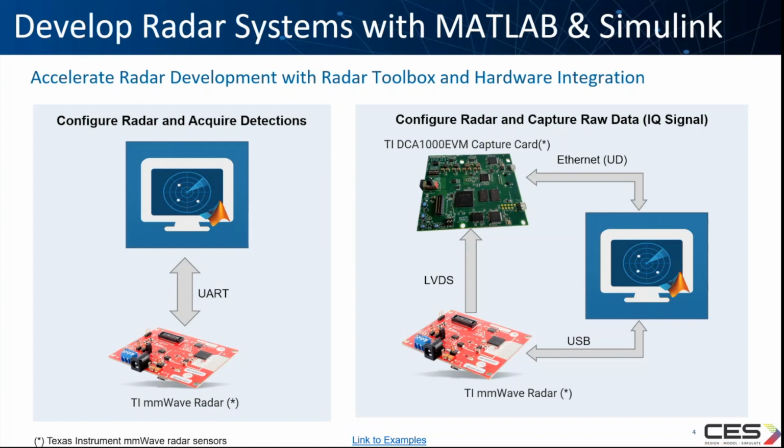MATLAB Radar Toolbox with Texas Instruments millimeter wave radar integrates in two different workflows. If you are designing and testing some clustering and tracking algorithms, you can configure and acquire detections from the Texas Instruments millimeter wave radar directly to MATLAB and perform these tracking and clustering algorithms or any data analysis algorithms.